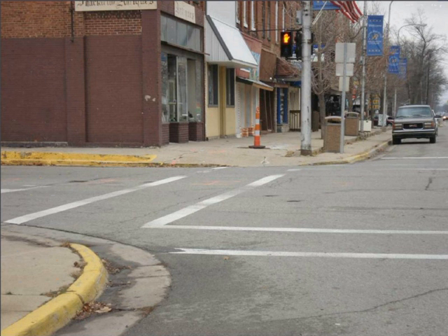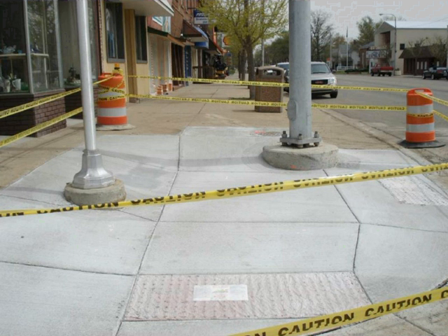Here's another example, anywhere USA. You always have tight right-of-way, buildings up close. You've got utilities all over the place, and this sidewalk is actually about 1.5 feet higher than the street, so that's going to really play into your ramp slopes. And this is what happened when the consultant designer looked at the standard and tried to force that standard plan in this situation. At the very bottom, everything's fine. You've got nice flat ramps, nice turning spaces, detectable warnings. But beyond that, it just doesn't work.